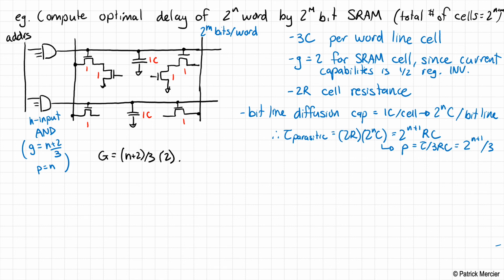So we're going to just take a guess here. We're going to set the electrical effort H to be equal to 1/2. This is a guess. It depends what we're loading the circuit with and so on, but it's an educated guess. It's something reasonable to think about.